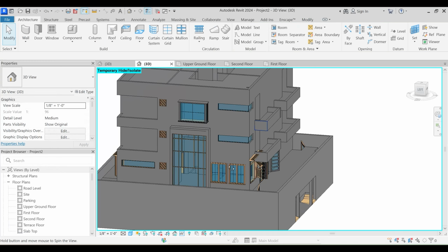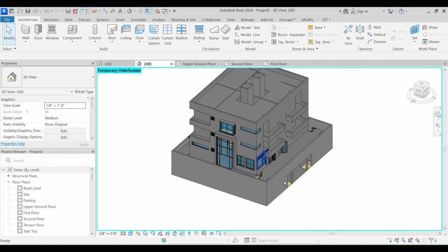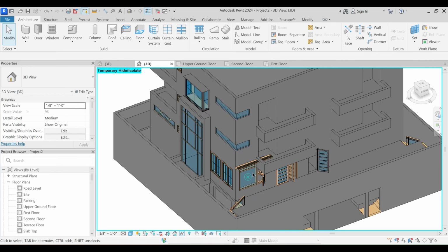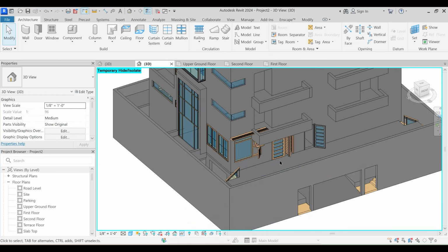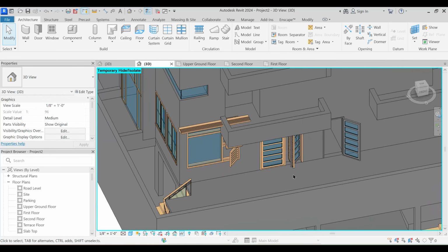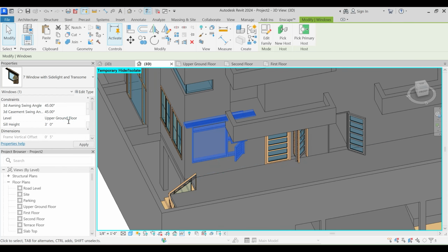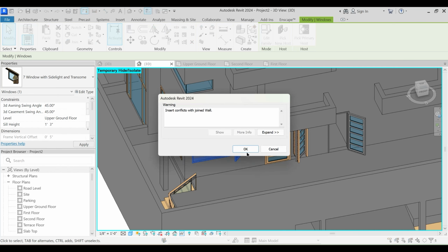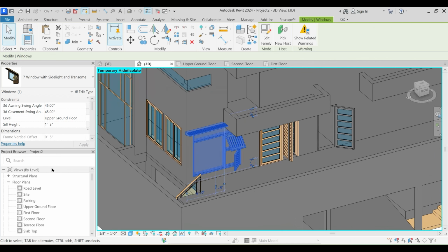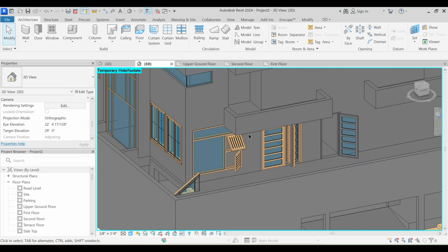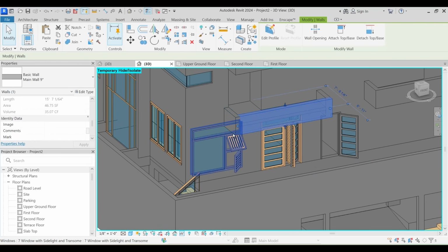Okay, perfect. So that is how you work efficiently in Revit. The next step is to deal with this particular parametric opening. Herein, I will just say that the sill height should be 15 inches. Sorry, not 3 foot, 15 inches. Yes, and I would just like to get rid of the sunshade. Fine. Okay, and this beam is creating a problem.